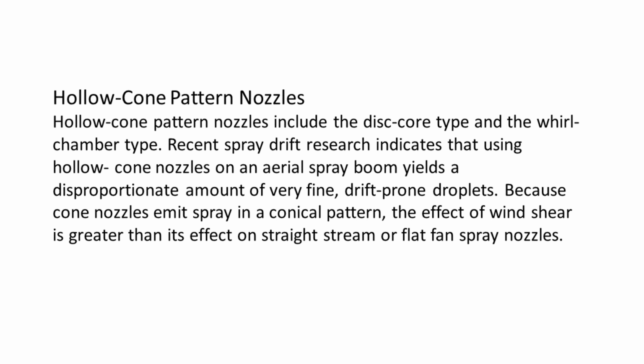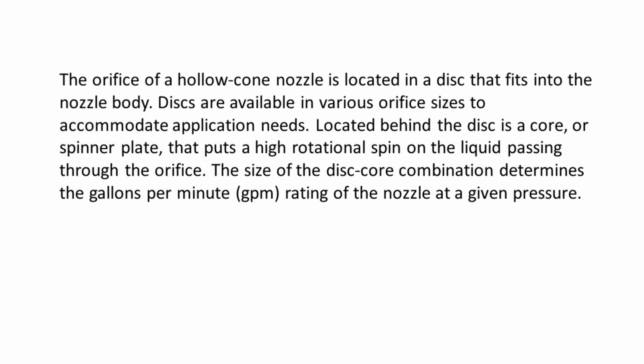Because cone nozzles emit spray in a conical pattern, the effect of wind shear is greater than its effect on straight stream or flat fan spray nozzles. The orifice of a hollow cone nozzle is located in a disc that fits into the nozzle body. Discs are available in various orifice sizes to accommodate application needs.